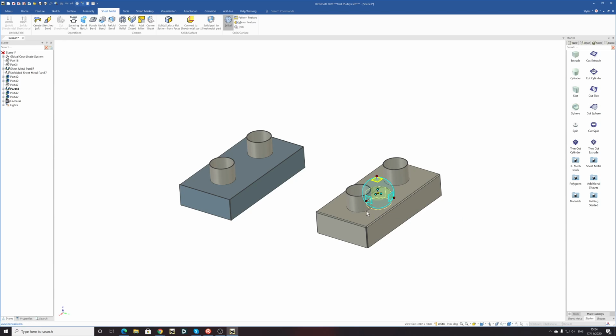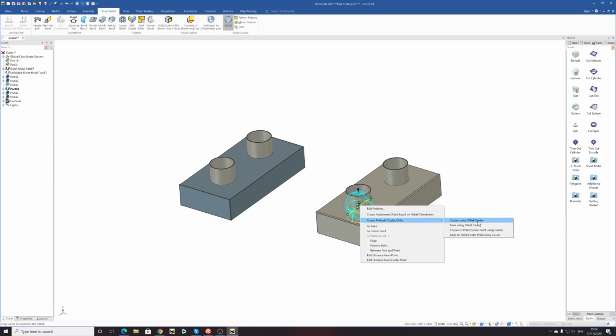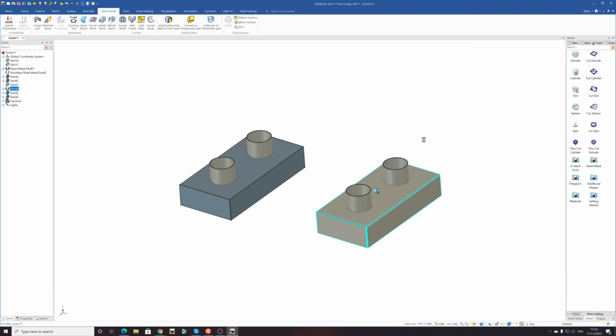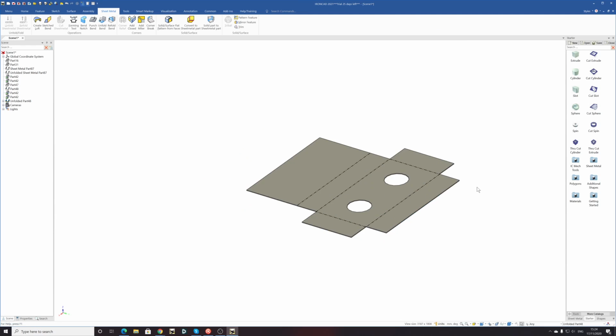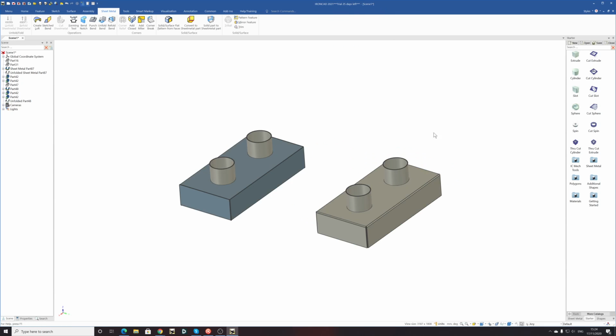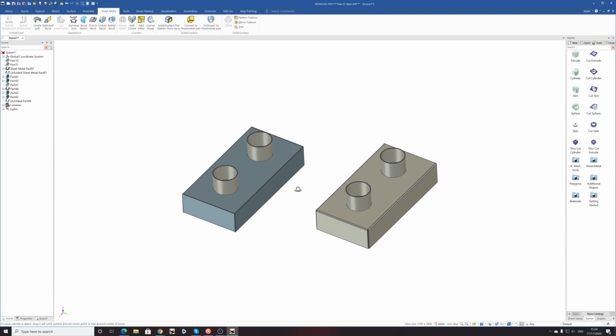I want to go to the center point of that, and I want to go in that direction, and I want to do the center point of that. Turn off the triad, and then I can pick on this and say unfold, and there you have our holes already done for us. So that was just two ways of creating the same box using two different methods.